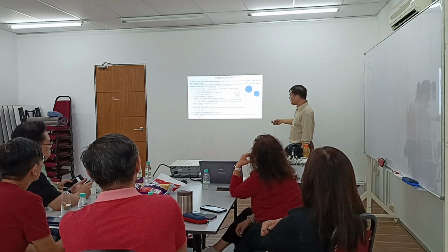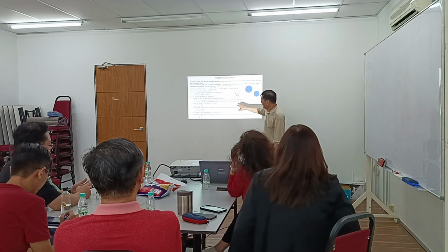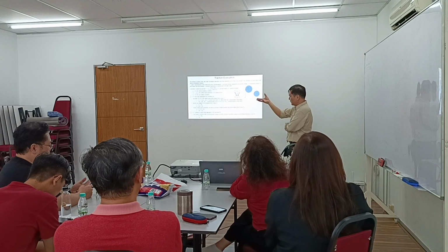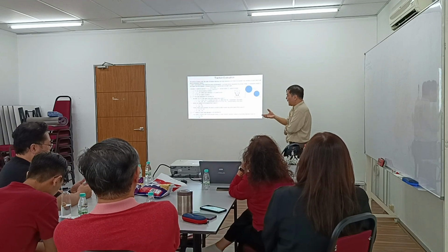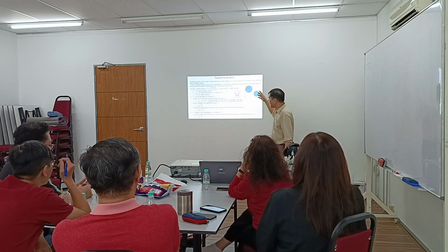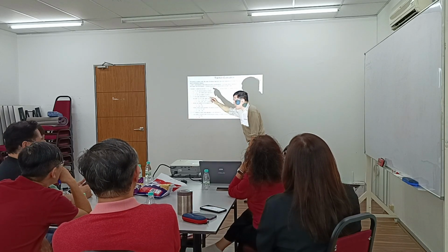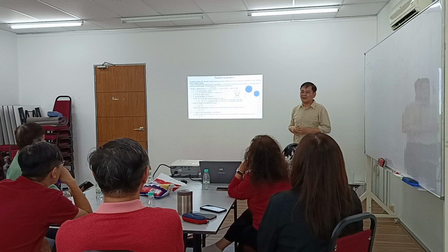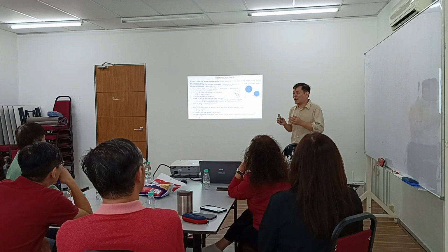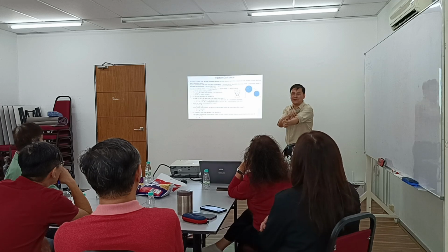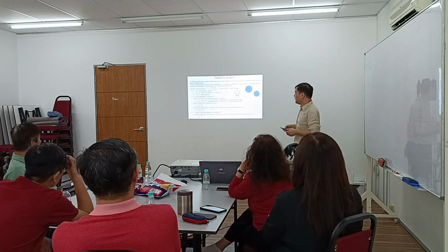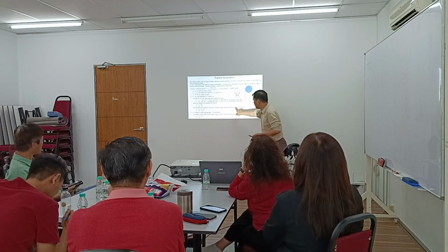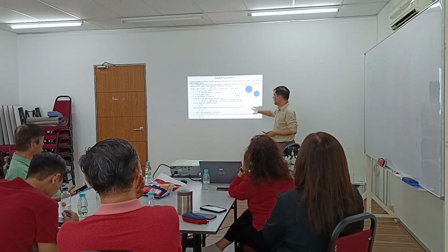Okay. Then we have also evaluated different corner cases: when the lift car is at 125% of the rated load at the lowest floor, and then the empty car at the highest floor. Why? Just now I talked about 10%, but for the traction evaluation I talked about 125%. The reason is just to give more allowance or margin, from the engineering standpoint. Then during the safety gear operation, when the car is at the lowest floor, it also cannot spin.